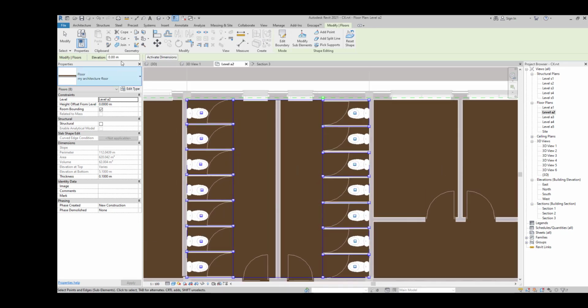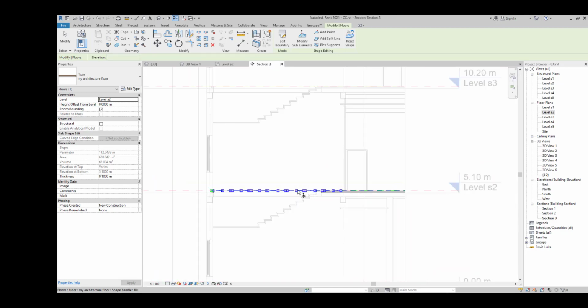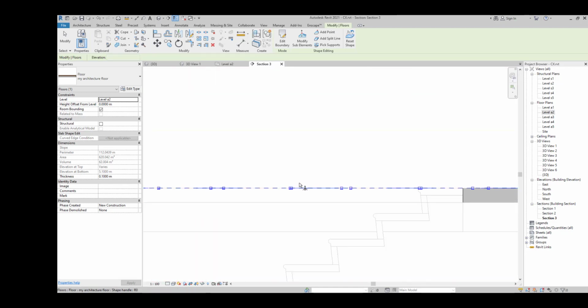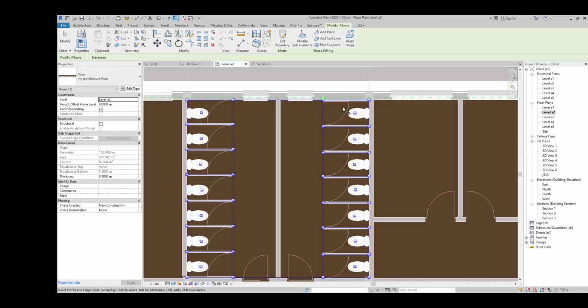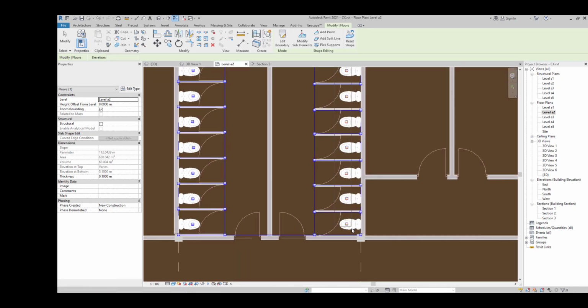Here we go, and I can add elevation here -2 centimeter, because we have 5 centimeter for our finish one. So I will click somewhere and hopefully we changed it. Let's check it again. So we select this point, the value -2 centimeter.